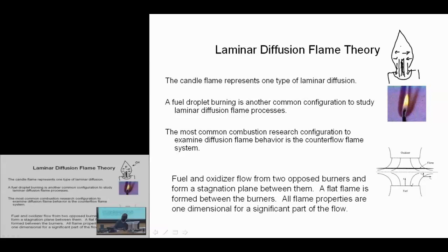So that's one scenario. Another type of diffusion flame is a droplet flame. For example, if you were examining in detail a compression ignition engine, a diesel engine, there's a fuel spray. There's an atomizer that sprays fuel into this hot environment, and you get ignition of these.